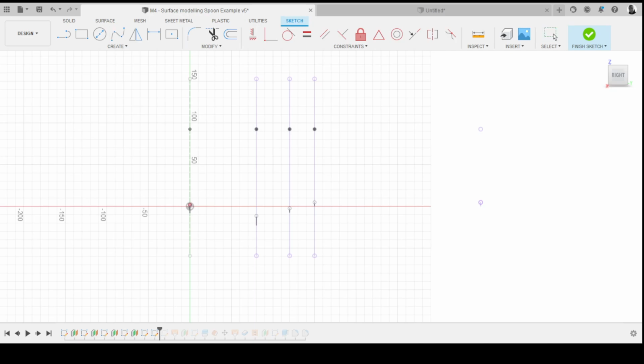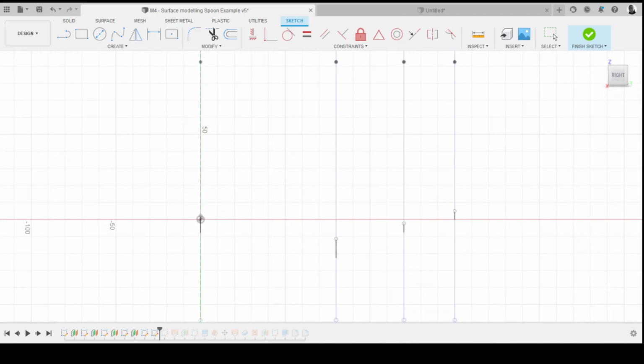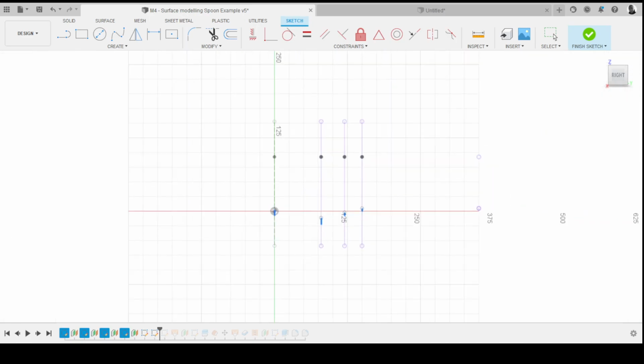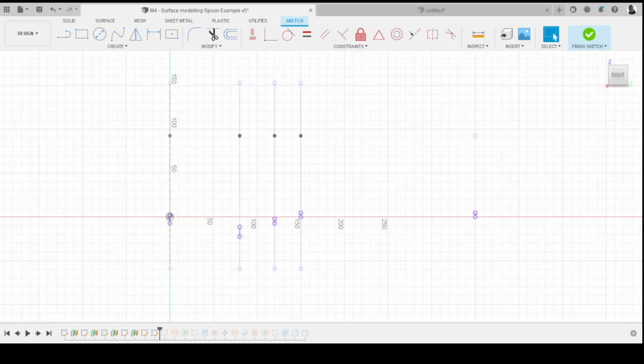So all I did was to go through these particular, I think it was the bottom. Let's just select the whole thing, these lines here. And all I'm going to do is bring in that geometry to this sketch. You can see we've got these little purple dots. Now I can snap my guide rail to those, and that's always the really important bit to remember to do.